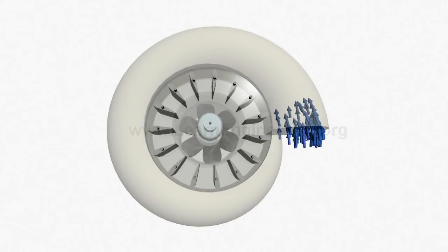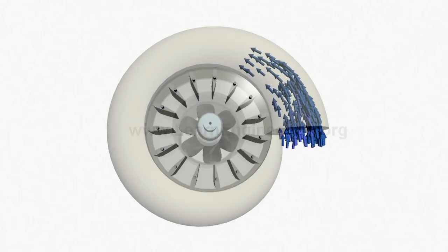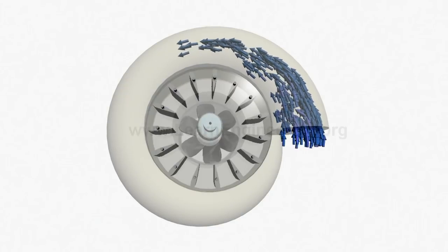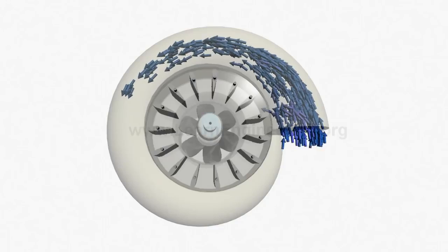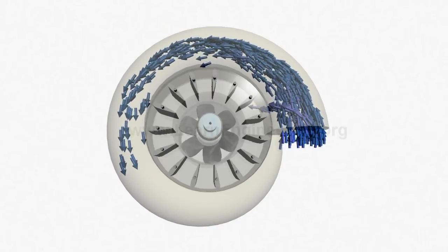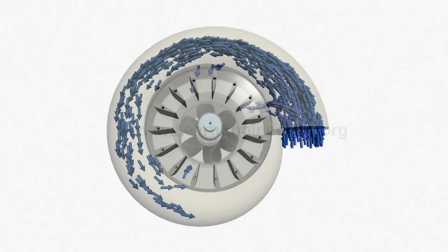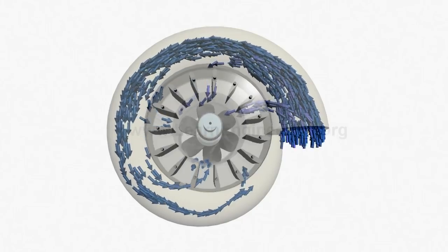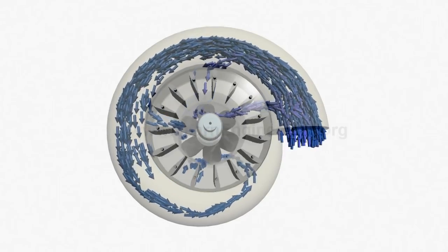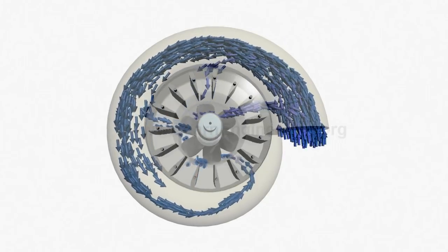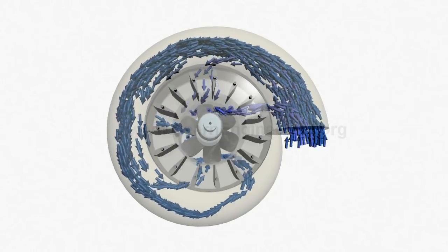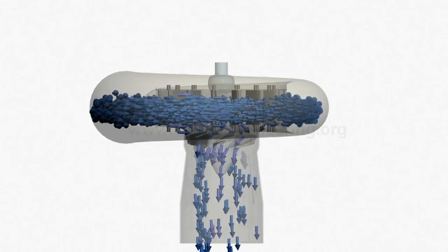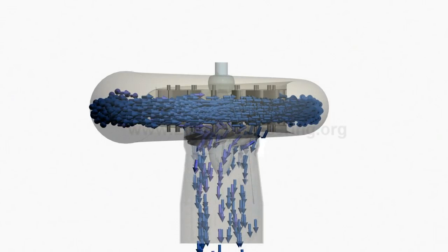In a Kaplan turbine, flow enters through a spiral casing. The decreasing area of the casing makes sure that flow enters the central portion at almost uniform velocity throughout the perimeter. Water, after crossing the guide vanes, passes over the runner. Finally it leaves through a draft tube.